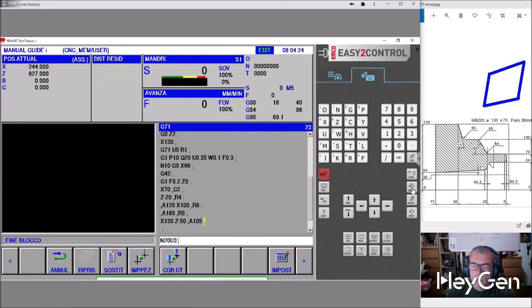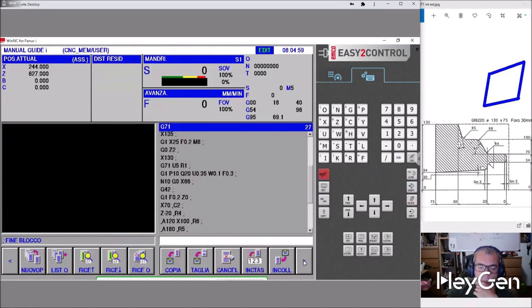And EOB. What is it? U3 is an incremental command that just raises me a little bit, providing a slight adjustment to the current position. N20 is my Q20, which is a reference point in the program. G40, EOB, insert G0. X300, Z300. These are specific commands that set the tool position to X300 and Z300, ensuring the tool is in the correct starting position. To avoid an alarm, which could interrupt the process, we add an M30 command, which is essential for program termination. Let's do our first simulation and see if we have any small errors.